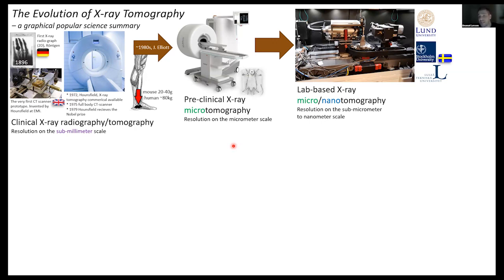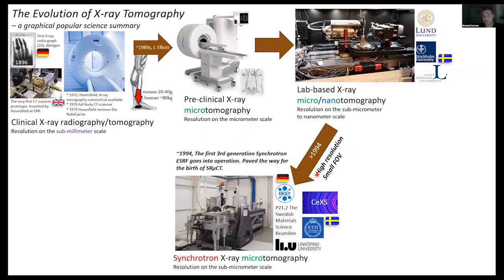So they also invented another version, microtomography, where instead of having the sample lying still and having a detector around and X-ray sources circulating, one has the X-ray source fixed, the camera fixed, and instead one rotates the sample. And then with the invention of synchrotrons and synchrotron radiation, this technique, microtomography, could move into the synchrotron.